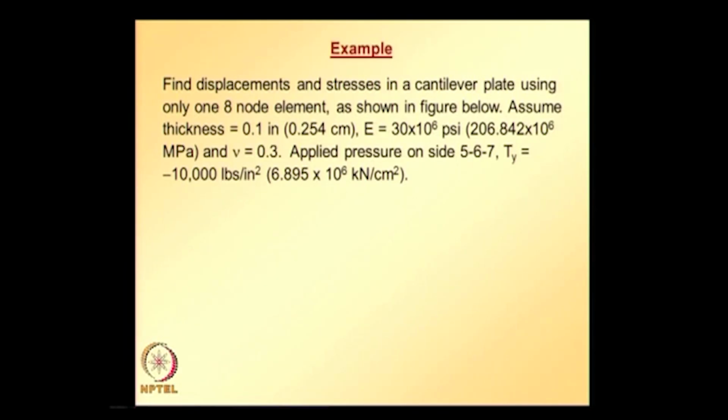The difference from the earlier examples, the 3 node triangular element and the 4 node quadrilateral element, is that there we had concentrated forces, so it was not required to evaluate the equivalent nodal load vector by integration.